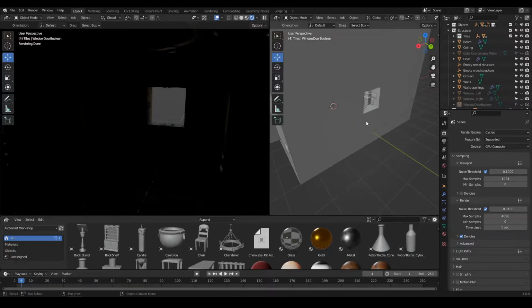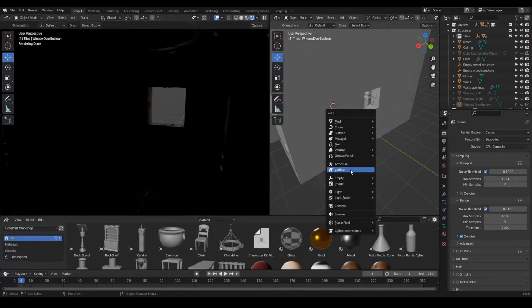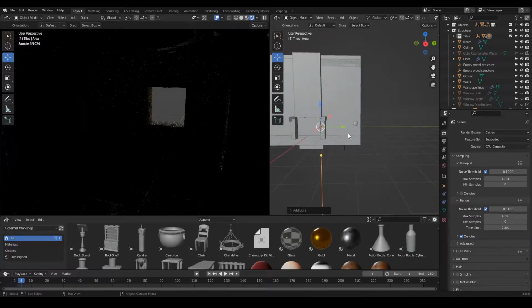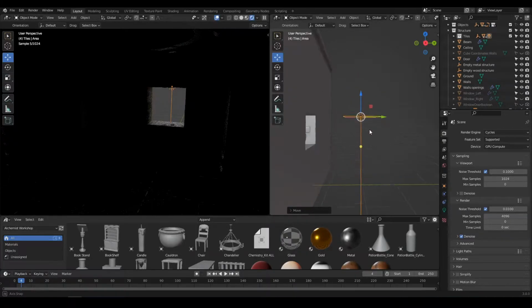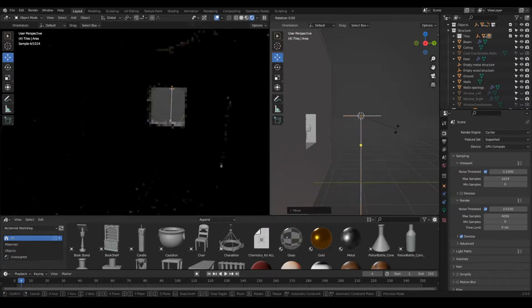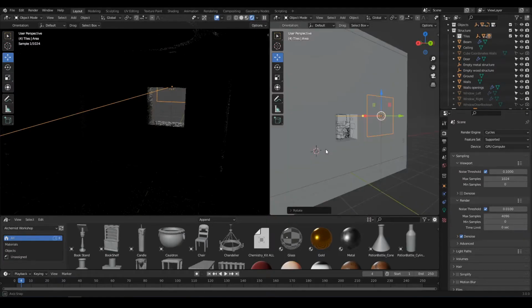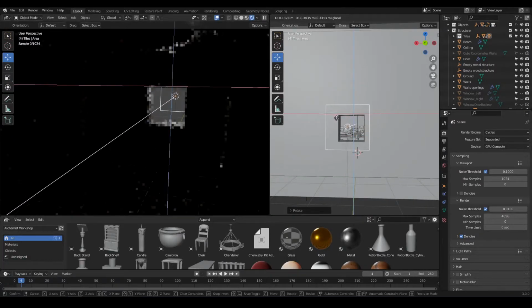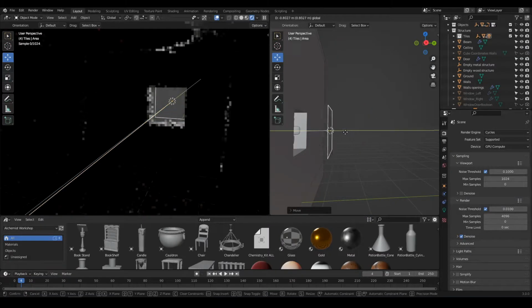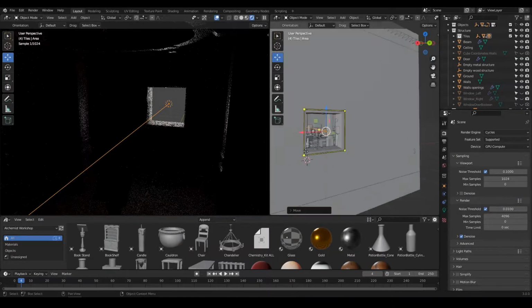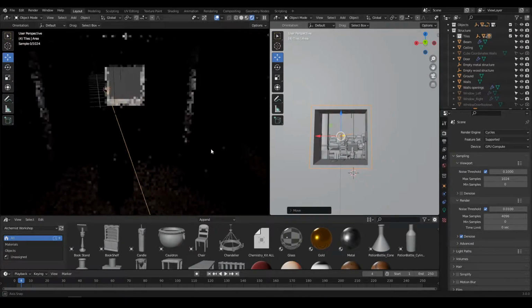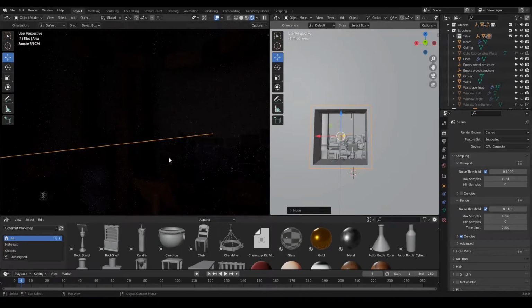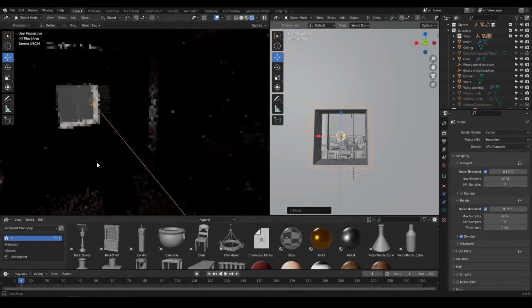Remember, the light type we talked about that was good to simulate what's going through a window is an area light. So I'm going to create one and set it right in front of the window. Okay, like this. This will help me to simulate light coming inside. You can see that now we can see a bit more inside.